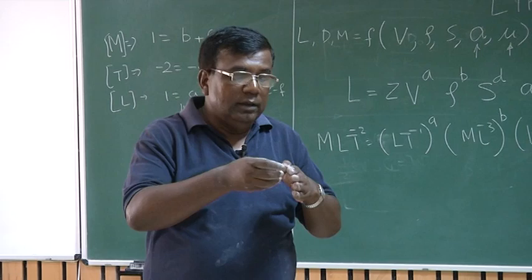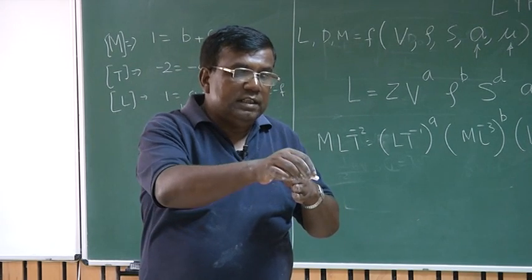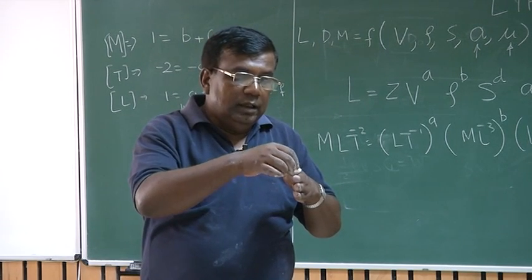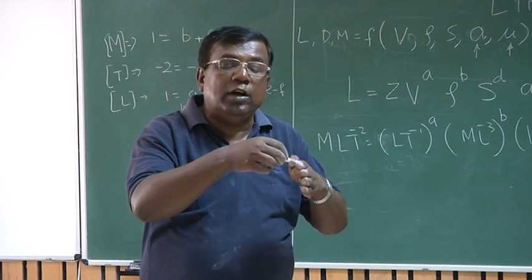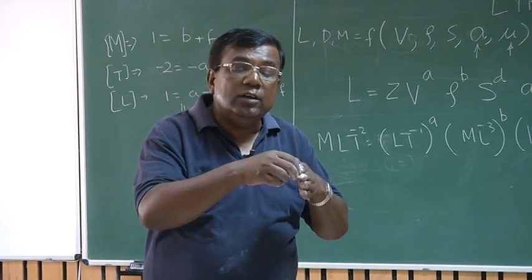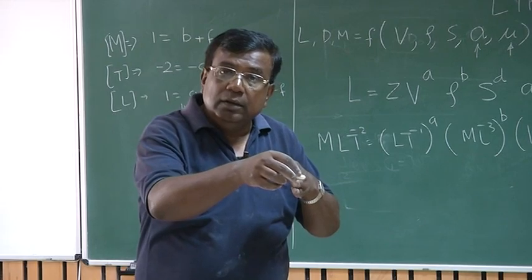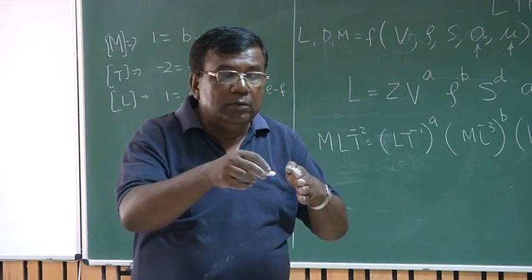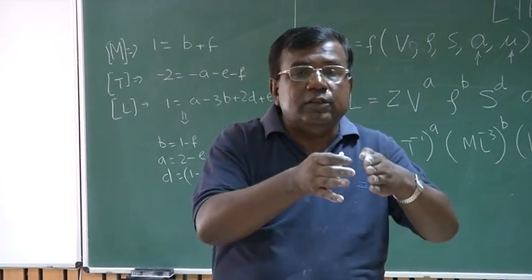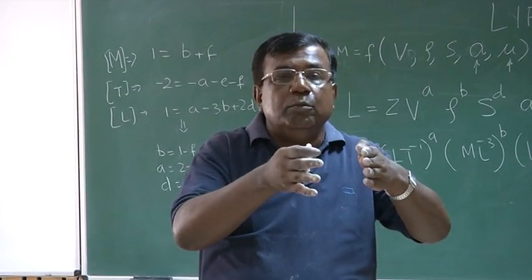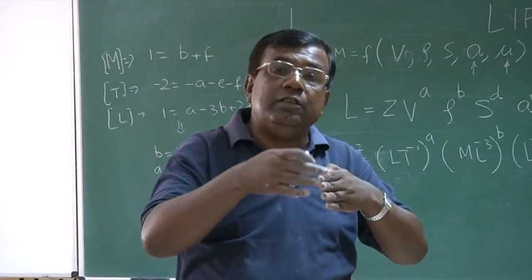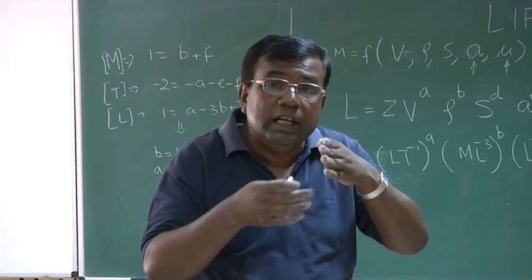So what will happen? Before the body reaches another particle, this disturbance will reach there earlier, because the body speed is less than the velocity of sound. So when it moves, the particles will arrange themselves based on the disturbances they have already received before the body has reached there.